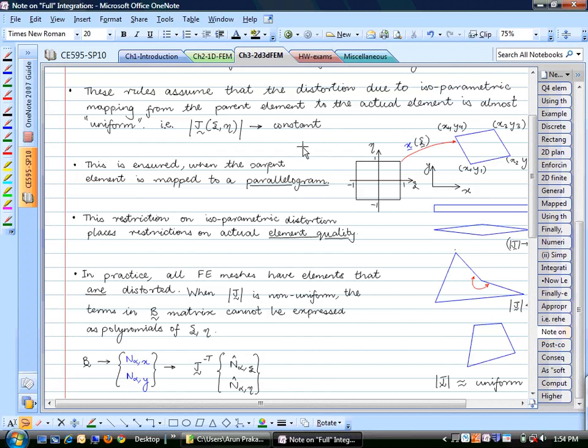But this condition, what is the minimum order of quadrature required? This is something for people who write finite element programs. So if you were to develop a new element instead of a Q4, let's say a Q20 or something, a huge element with lots and lots of nodes, then you would want to make sure that it integrates the Jacobian exactly. That's the condition that makes sure that your finite element mesh with a new type of element, if you make up a new type of element, would converge.